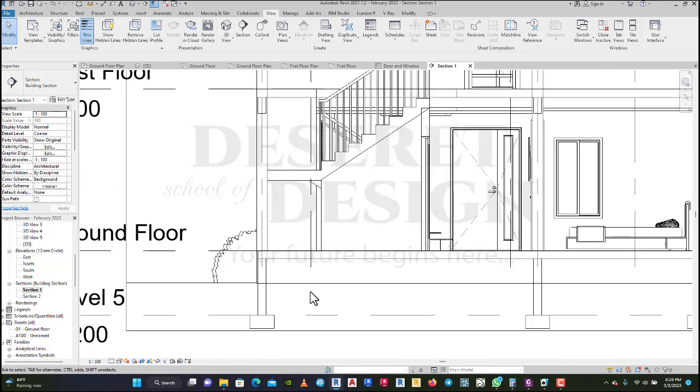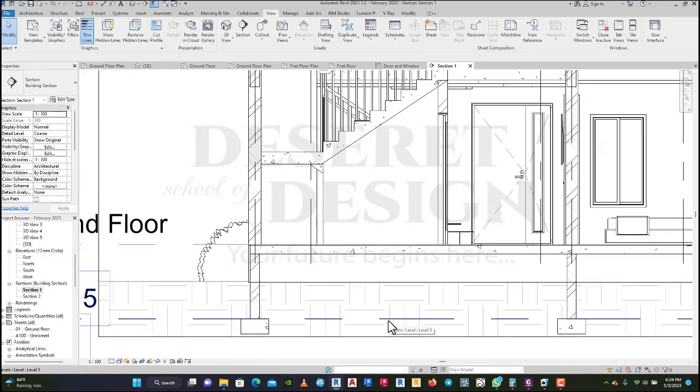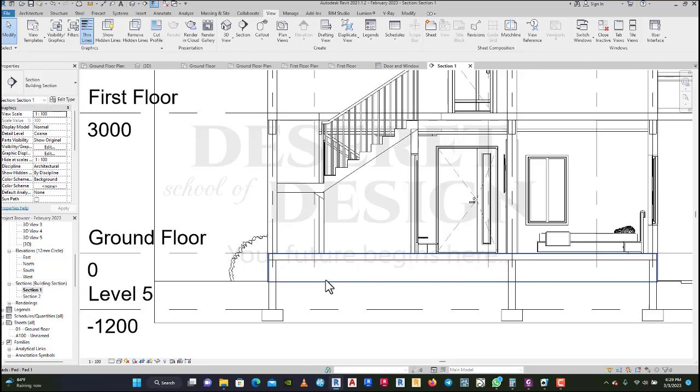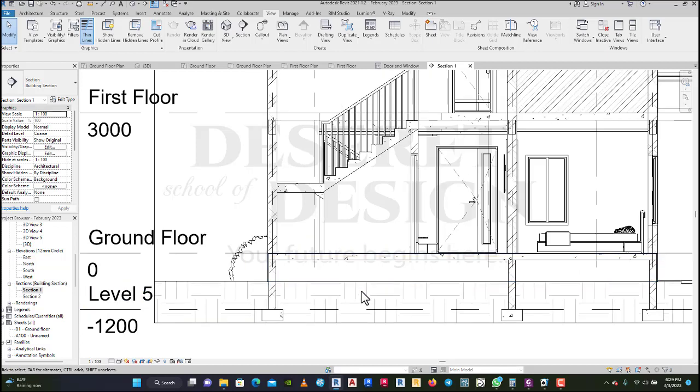Now you realize that in our foundation we might want to do hardcore filling, after digging and after the block, where you might want to fill to where the floor is. Now we don't have anything showing, so we need to represent our hardcore filling in it. Now how do you do that? We need to use what we call a filled region.